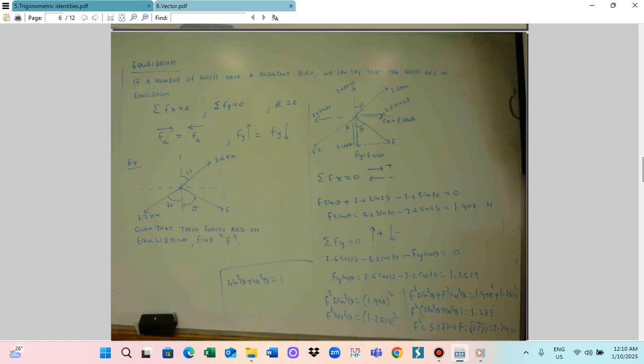So this is the Fy. This is the Fa. So Fa is F cos theta, Fy is F sin theta. So angle theta here. In this case, because of the angle theta, the FA is F sin theta and Fy is F cos theta. Because this FA here is the opposite side, and opposite side is sin theta. And this Fy is the adjacent side, so Fy will be cos theta.